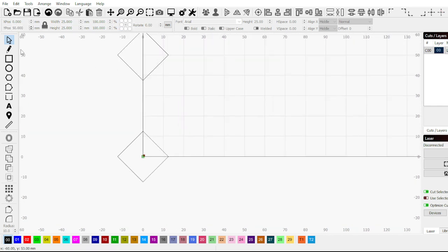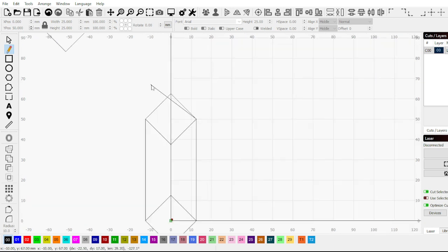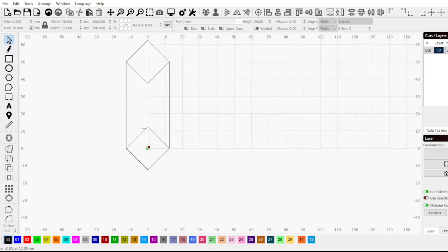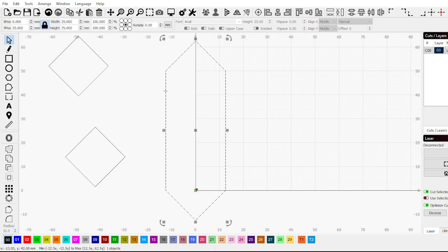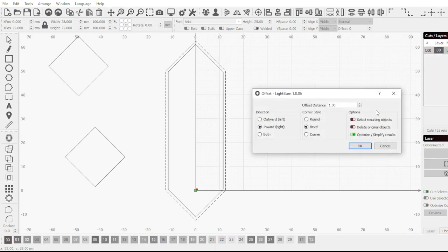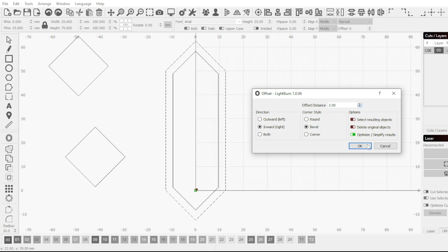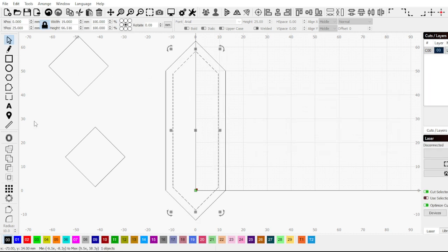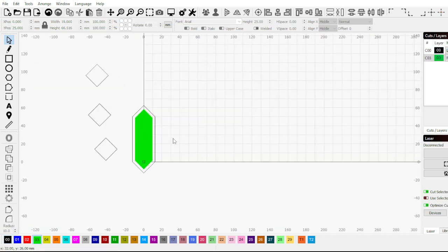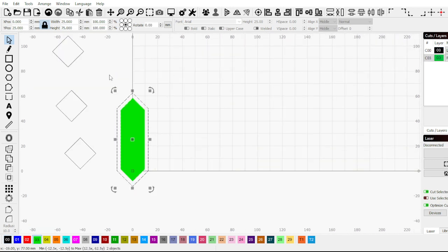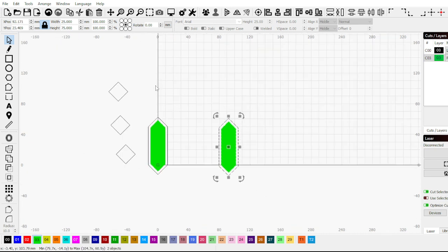and then make a digit out of this, let's see what that looks like. So grab my line tool and wait till it locks onto points and edges. Okay, there we go. And then we actually don't need to delete these. We can move these out of the way. Okay, so that's the actual window. And then let's do like 3 millimeters inside. Okay. And then do this, if it's all the way green, so that'll be one digit, right? So then I Control C, Control V, Control V, Control V.